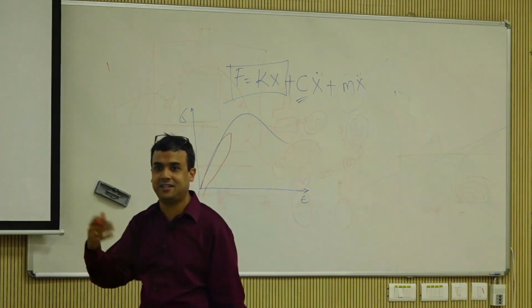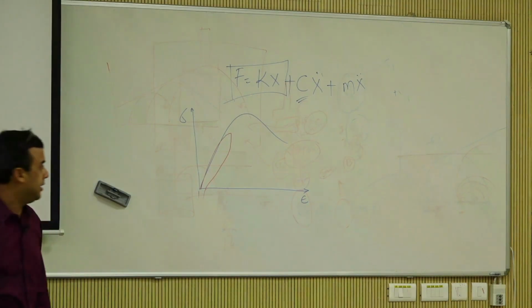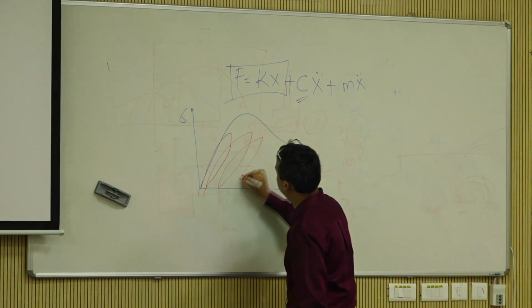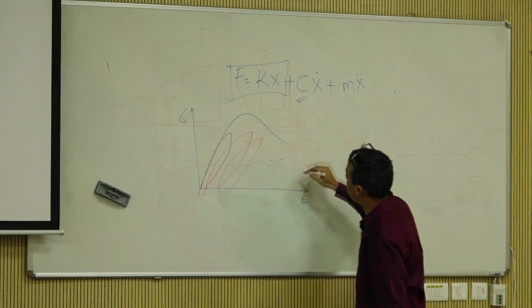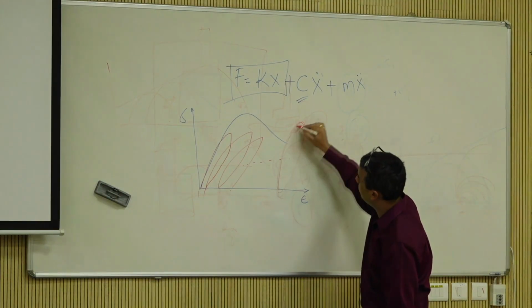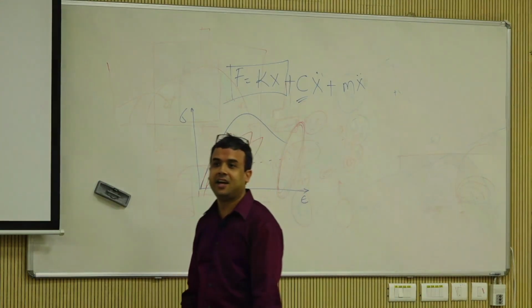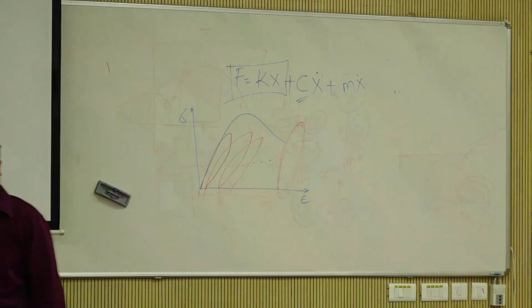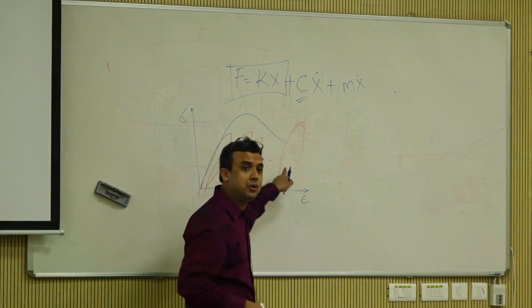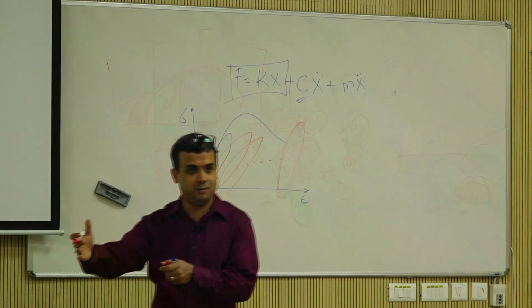It's going to have some plastic deformation, right? Next cycle, come back, do many cycles. At one point, you go into what is known as a hysteretic behavior. There is no further permanent deformation accumulation. That elastic stage is what we are going to talk about, the resilient modulus and resilient stage.